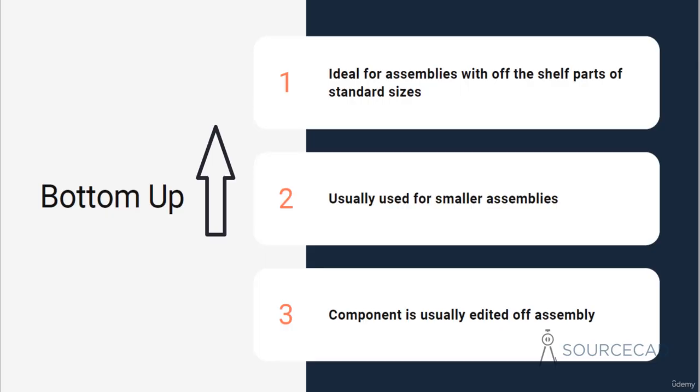Now it is also recommended and also used for smaller assemblies. And if you want to edit the components, in this case, you can go to the actual part, edit the component, and you can then regenerate it directly in the assembly.